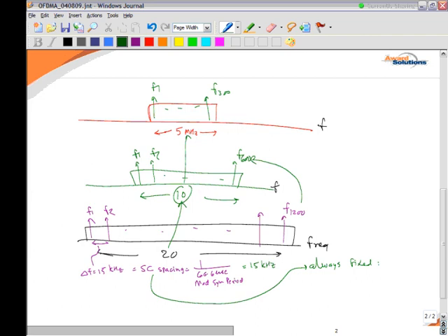It means that if you have larger spectrum bandwidth, you have more subcarriers. If you have narrow bandwidth, you have fewer subcarriers. This type of OFDMA system is called a scalable OFDMA system. You are scaling the number of subcarriers based on the available bandwidth. Narrower spectrum bandwidth, fewer subcarriers, and wider spectrum bandwidth means more subcarriers. That is the basic idea.